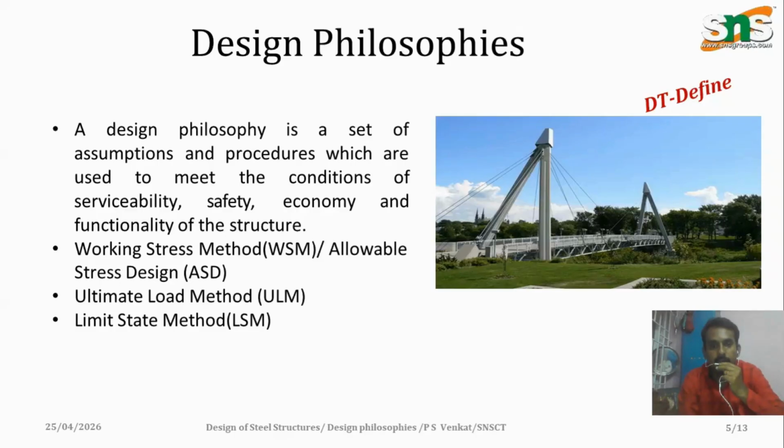Design philosophy. A design philosophy is a set of assumptions and procedures used to ensure safety, serviceability, economy, and functionality of a structure. There are three main design philosophies: working stress method, ultimate load method, and limit state method. In this session, we mainly focus on the first two.